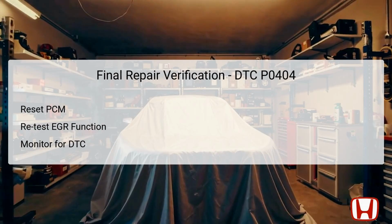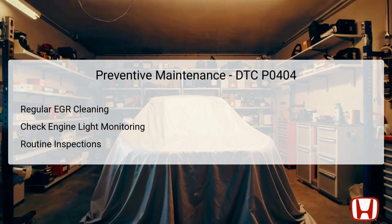Following this, continue to monitor the system for the reappearance of the DTC P0404. If no errors return after several driving cycles, the repairs can be deemed successful. Preventive maintenance plays a significant role in mitigating the recurrence of DTC P0404. Regular cleaning of the EGR valve and related passages helps to ensure that no carbon buildup impedes function.